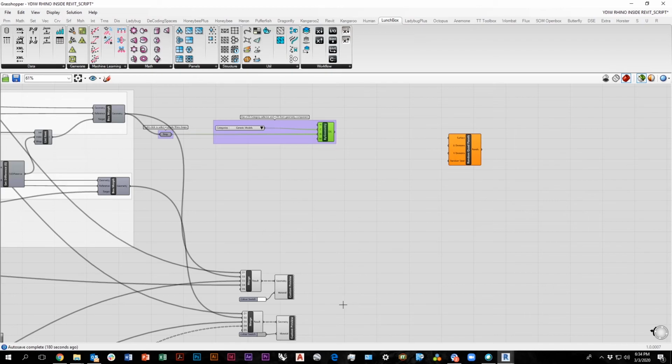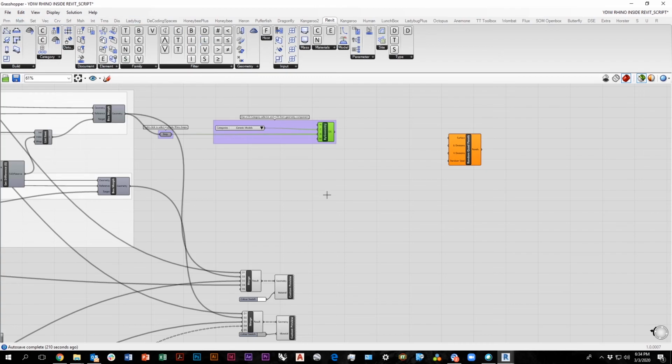Well, if you model every aspect of a building, it'll crash your computer or be super heavy. So the information is still there that it's a 4 by 2 by 4 with 8 foot spacing between them. It's just not going to model it for you to see unless you turn on detailed view or go into a 2D drafting view and represent it that way. But it's not going to draw the model at full resolution of the building. So the information is still there, and you can probably extract that information and use it as part of your Grasshopper script to do other things, which is so awesome.